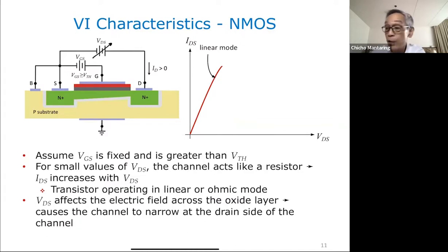And the reason for that slope is here, the N to P reverse bias is going to be greater than here. Along the oxide layer, you have a smaller electric field here than here. The electric field here decreases because of VDS. So originally we had a VGS applied. You have VGS applied uniformly here, no? So you have VGS here, but here in the bottom you have VDS.